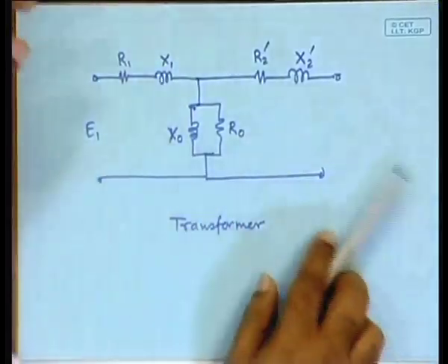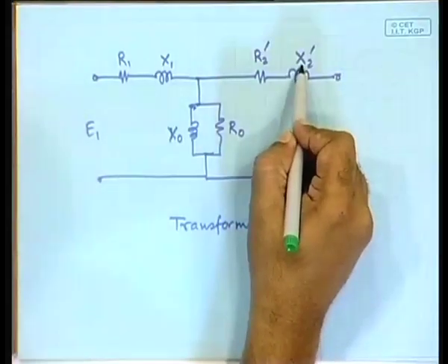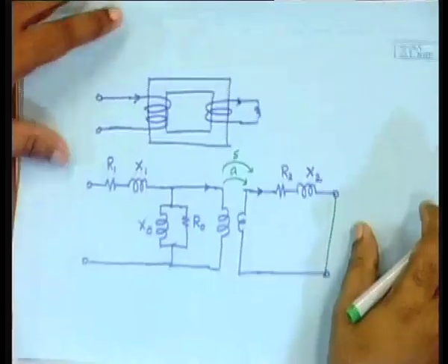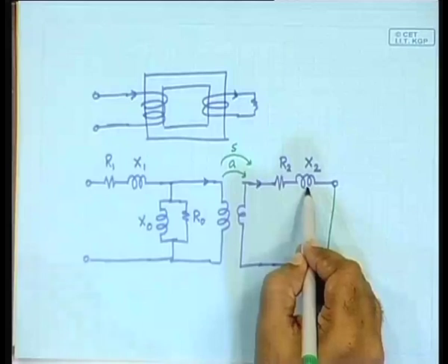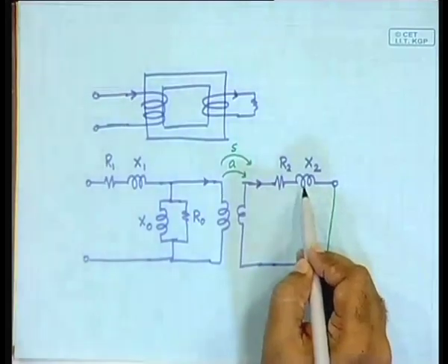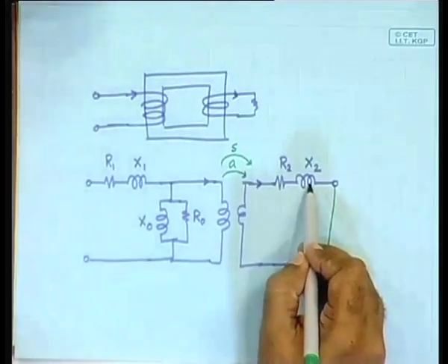Notice one thing, if there is a coil with some inductance, what will be the inductive reactance? It will be proportional to the frequency, right? So, whatever this fellow's value was, if it is connected directly to the 50 hertz supply, it will not be the same value, because now it is experiencing a far lower frequency.